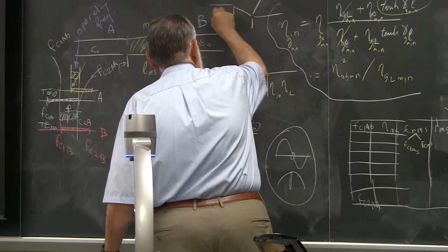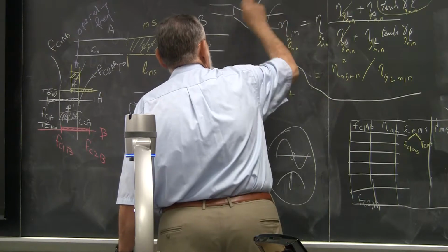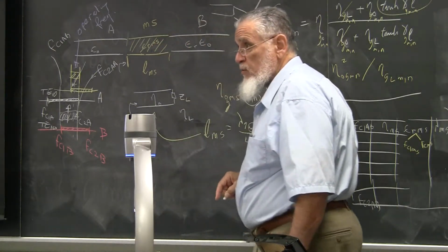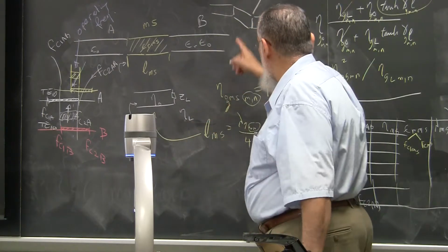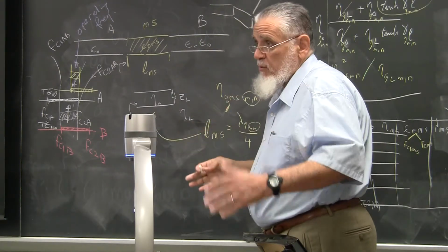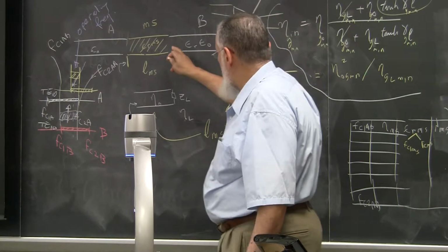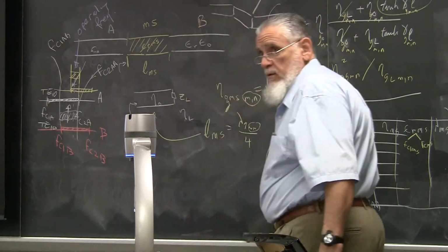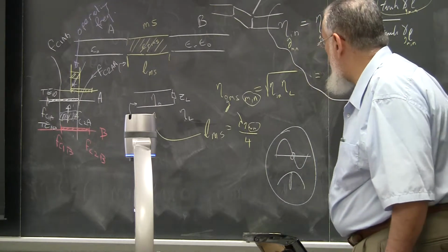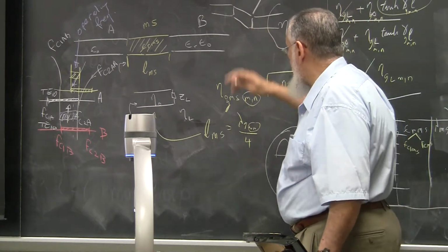You may have a situation where you design guides this way, okay? These are also possible. Two different guides, different cutoff frequencies, and your matching section will be tapered. Now, this particular case here, they are all the same dimension and different filling, okay? Just to be aware of that other possibility here.